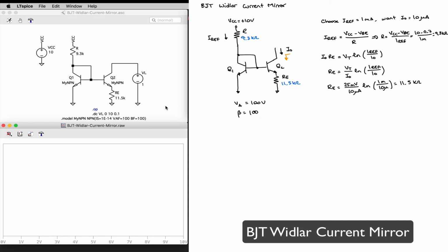And again, I'm expecting my output resistance, in this case, to have the same form as the emitter-degenerated current source: little r2 times 1 plus gm of transistor 2 times rπ2 in parallel with the emitter resistor connected to transistor Q2. I can go ahead and calculate those numbers.